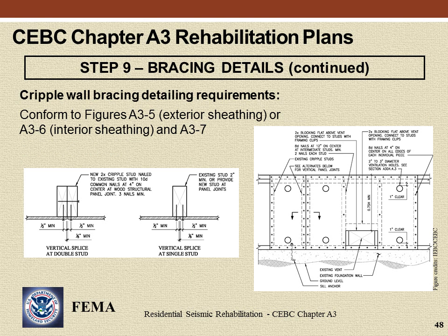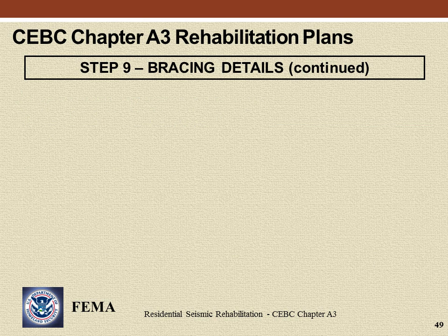Figure A3-7 shows additional details of cripple wall bracing that must be used with either detail A3-5 or A3-6. Alternate details for vertical joint at abutting plywood panels. 1. Install the 1/8 inch gap between abutting panels to allow for expansion with moisture change. 2. 2 2x studs or 3x studs are alternatives. Vent holes are required to mitigate moisture buildup in stud cavities. Rodent screens on vent holes are suggested.